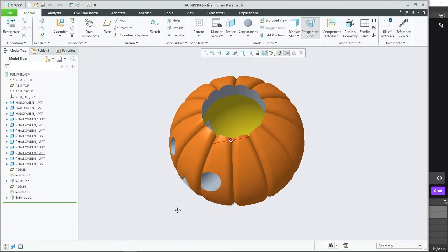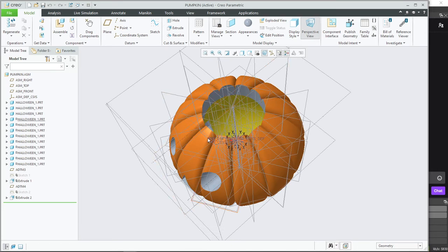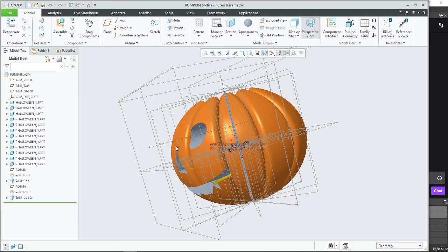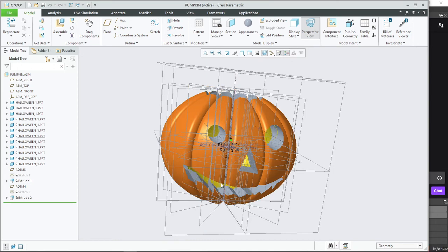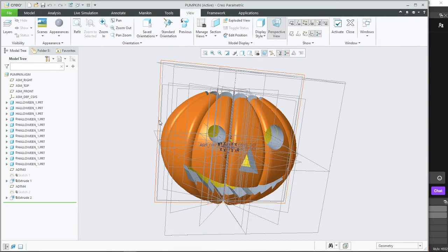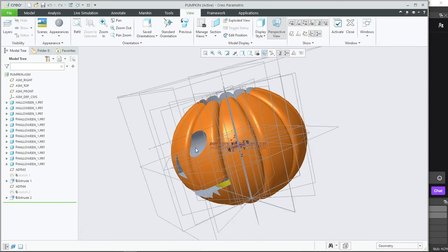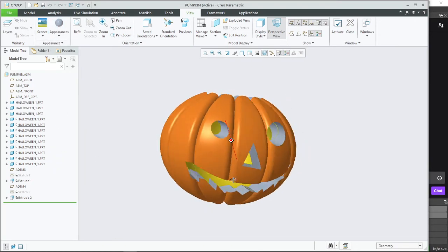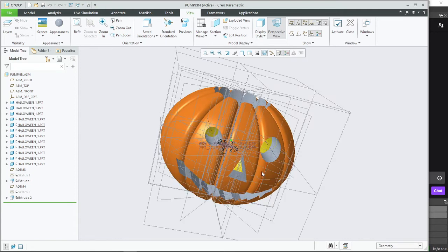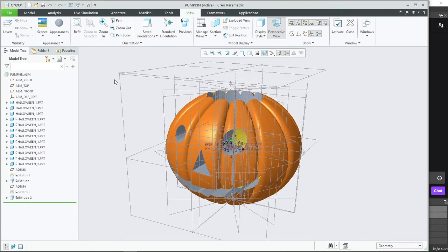Now, the reason why these surfaces are not colored is because they came into existence here. So I would need to color them up here. But coloring in this workbench colors an entire piece, not a surface.